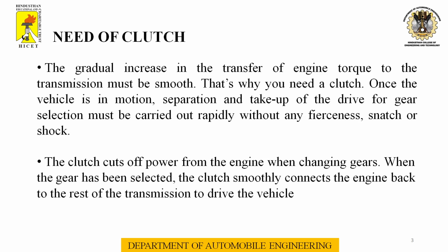The gradual increase in the transfer of engine torque to the transmission must be smooth. That's why you need a clutch. Once the vehicle is in motion, separation and take up of the drive for a gear selection must be carried out rapidly and without shock. The clutch cuts off power from the engine when changing gears. When the gear has been selected, the clutch smoothly connects the engine back to the rest of the transmission and to the drive wheels.